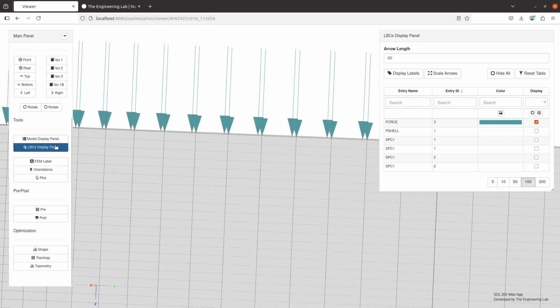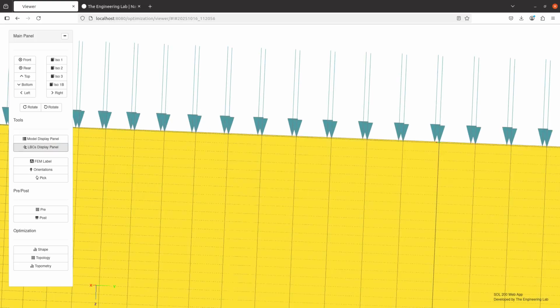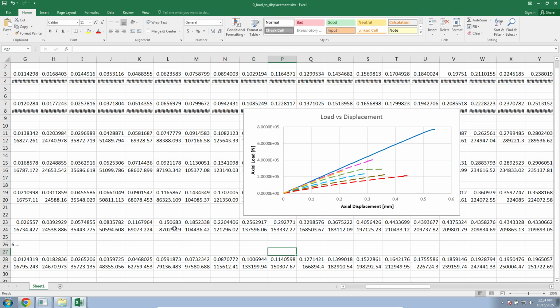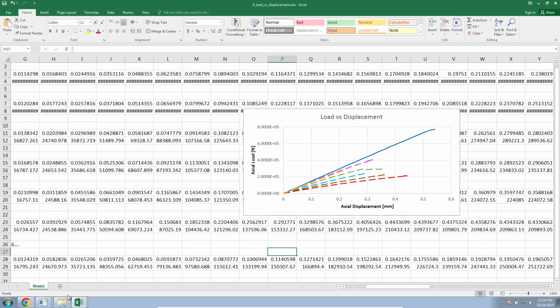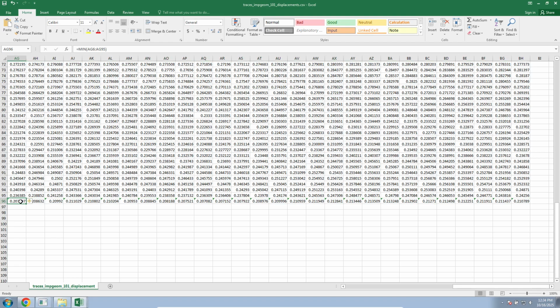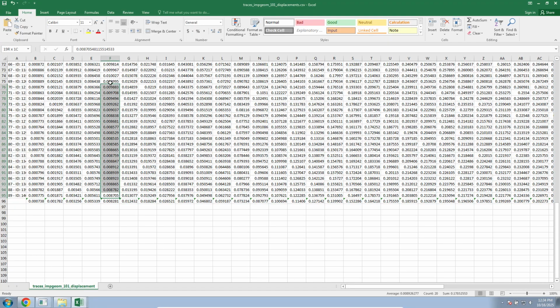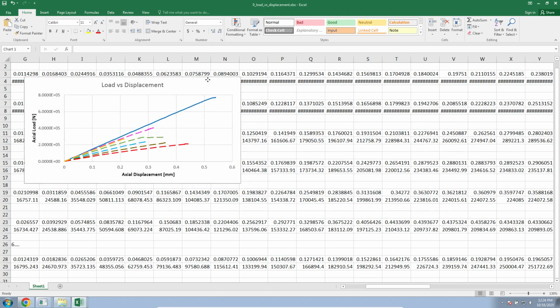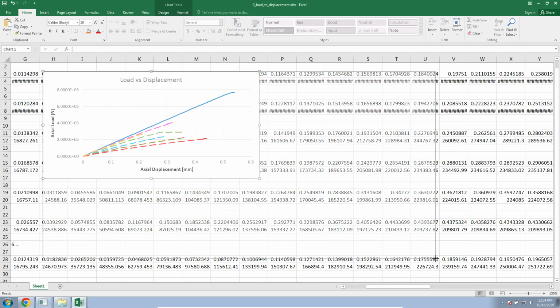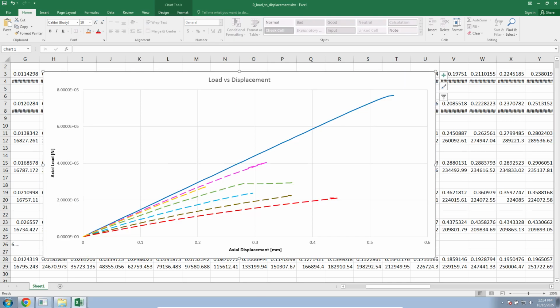So we got the time histories for all these loaded nodes, and then we determined the minimum deflection or displacement for every load step. If you recall, we used the min function here. We said for every node, for every load step, find the minimum, record that, and then that's what we use to create these plots. So there you have it. That's my interpretation about how they got those load versus displacement plots.